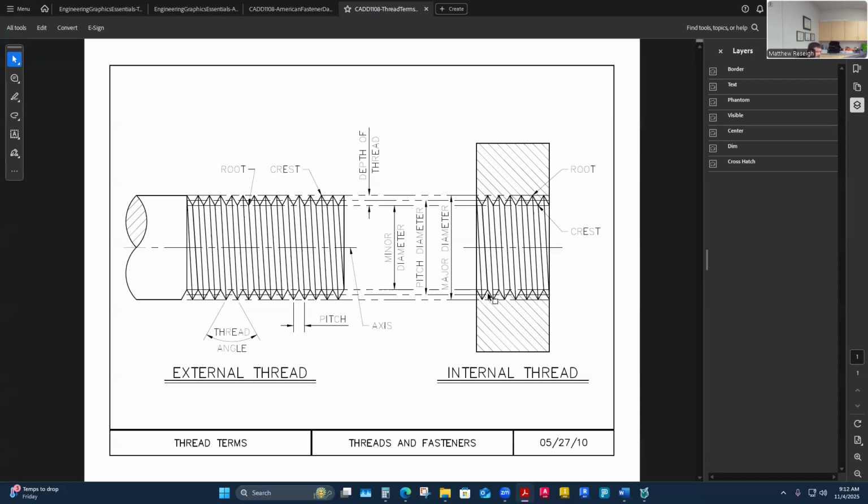Just a little side note that trips me out about this: when you take any bolt threads and thread it into an internal thread like this, the first three threads are taking something like 75 percent of the load. And everything thereafter is just a fraction of the load. So it's critical to have these things cut and fit right, because within the first three or four threads of engagement is where most of the load is being held. So it's super critical.